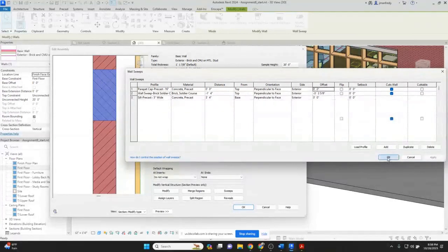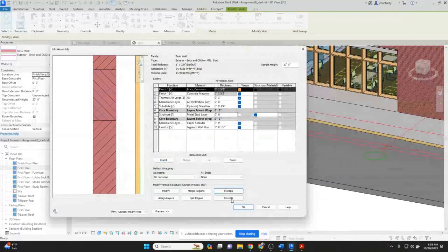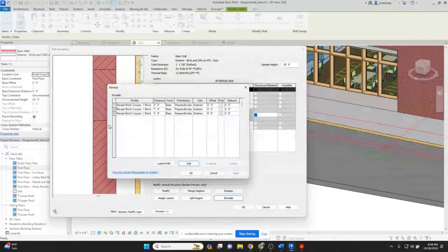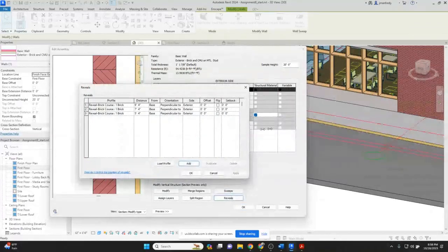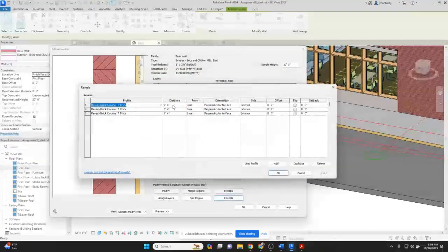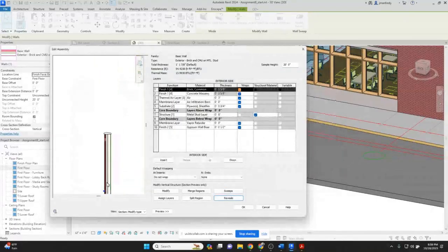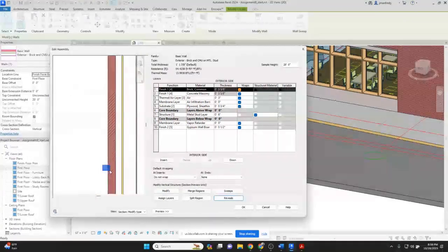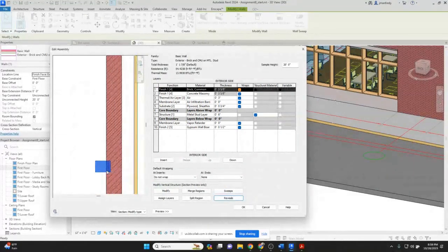And the same is true for sweeps. The sweeps are here, what they call reveals. Not sweeps, reveals. Basically, they're using this brick shape, which is a rectangle. These are the locations of the sweeps from the bottom, either from the top or the bottom, you decide. And then they are not offset. So these are the areas that are carving out these. This is a brick loaded here. It's carving that out right there. You can make your own custom sweeps and cut through a wall like that.